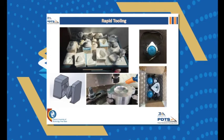14 molds can be produced within 2 weeks through rapid tooling. Now, to the bottom of that picture, you will see an aluminium insert being manufactured. Now, with rapid tooling, you cannot solely rely on additive manufacturing to create your molds. There will still be some subtractive manufacturing to be produced. So, in my opinion, there will never be a future where you can solely produce a mold with additive manufacturing.